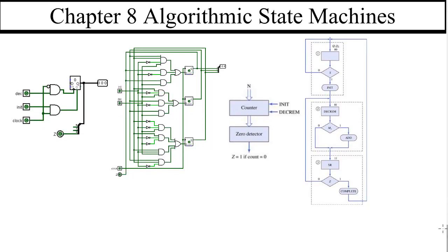And then here we have the counter circuit. The counter circuit is a problem because if you try to use the simulator's counter, it has this asynchronous input right here. So what I did is I redesigned the entire counter from scratch as a Moore machine. You can see the output is just dependent upon the flip-flops. So I had to draw a state diagram for this finite state Moore machine. So we started off right here.